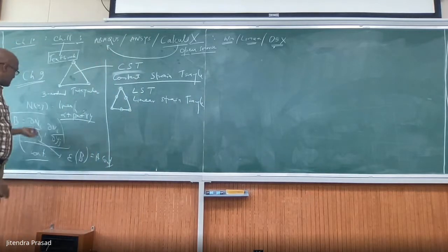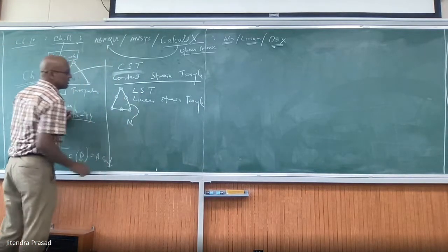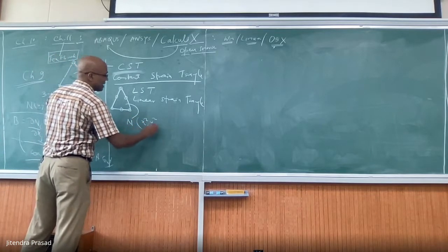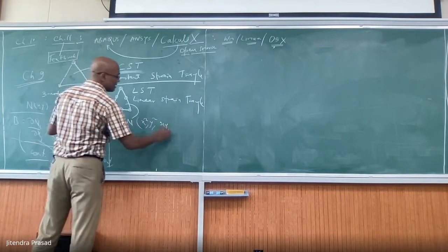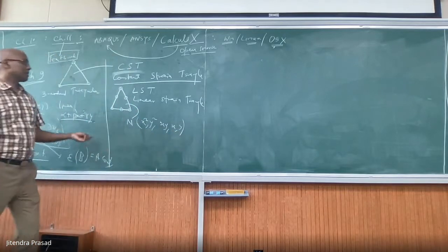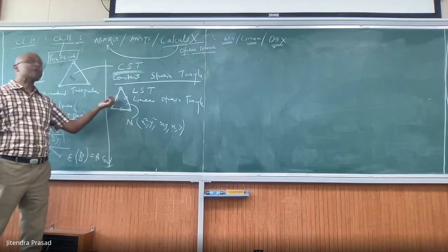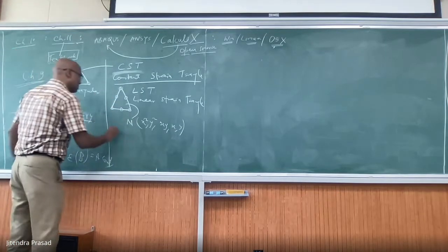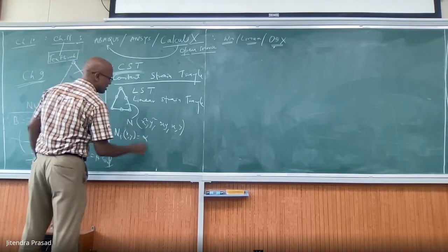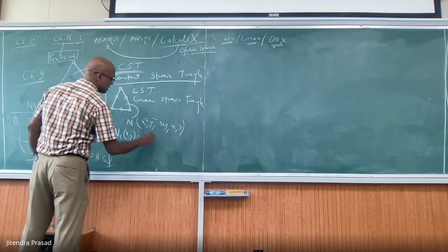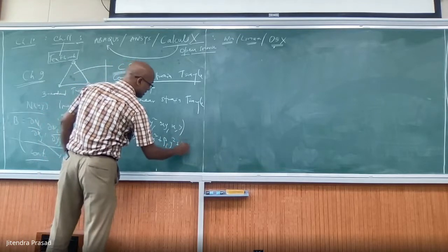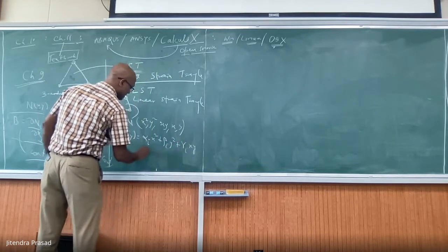And linear because in this case N will be a function of x square. So this is quadratic: x square, y square, xy, then x, y, and there will be a constant. So this will have all the terms. You can formulate it as N_i(x, y) equal to alpha_i x square plus beta_i y square, and so on. You can do gamma_i xy, delta_i